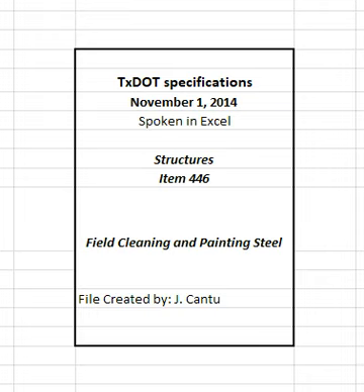4.7.4.2 Thinning. Adjust paint to the correct application consistency by using suitable thinners or by using properly applied heat up to 150 degrees Fahrenheit. Using heat to thin paints may decrease their useful pot life. 4.7.4.3 Paint system requirements. Ensure all coatings in the paint system, including shop-applied coats, are from the same manufacturer. 4.7.4.4 Stripe coat. All stripe coat, when specified, will be unthinned and worked in by brush to achieve a contiguous film over all edges, corners, bolts, nuts, threads, rivets, and weld seams, extending at least 1 inch onto adjacent steel.